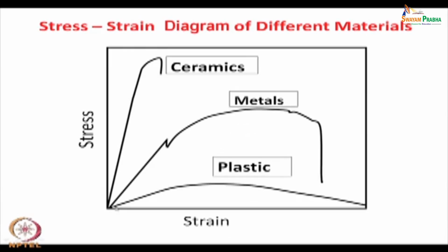And in plastics, of course, most of the time it takes a lot of strain even at a lower stress, and sometimes it breaks and sometimes it comes back, being a rubbery kind of material. So, our point of concern here is the plastic deformation range, how this plastic deformation takes place, because there is a breakage of bonds, or the bond length may increase, and then it is a permanent increase, it does not come back even if you remove the stress.